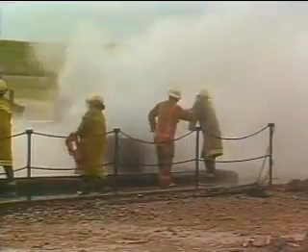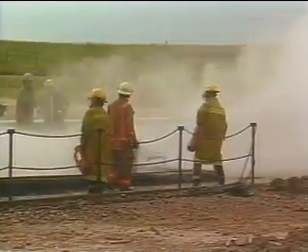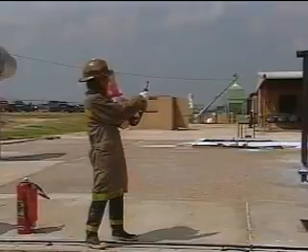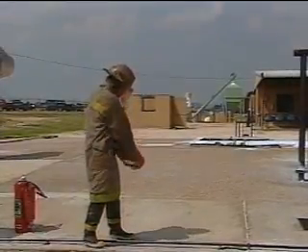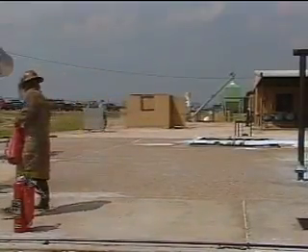After using a dry chemical extinguisher, gas it off. Turn the extinguisher upside down. Point the nozzle skyward, and activate the handle until the extinguisher is empty. This clears the valve and hose setup, and the extinguisher is less likely to clog when refilled.